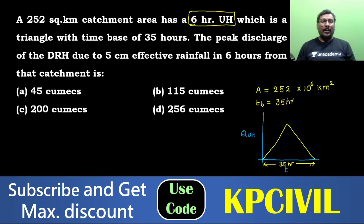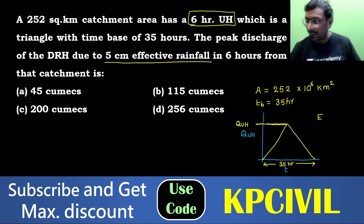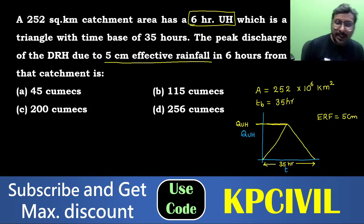Good. What is the peak discharge of the DRH due to 5 centimeter effective rainfall in 6 hours from that catchment? First we find the peak discharge of QUH, then multiply by the effective rainfall. The effective rainfall is given as 5 centimeter. Based on that we can estimate. Is it clear?